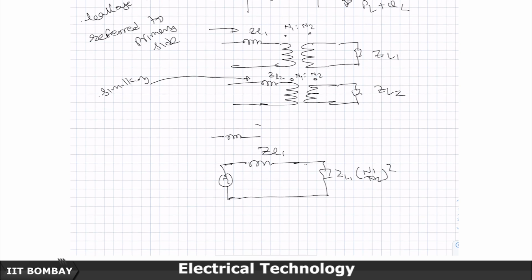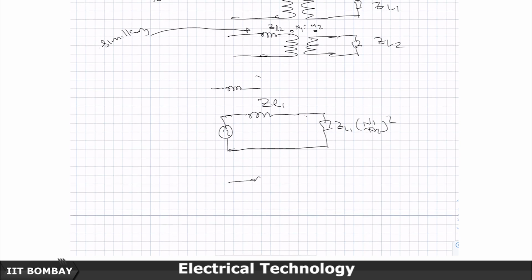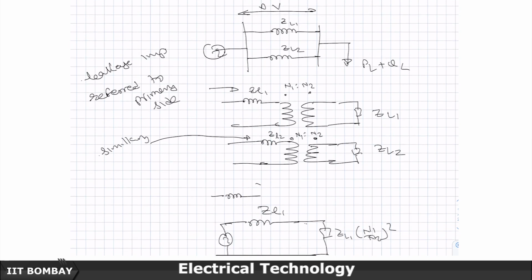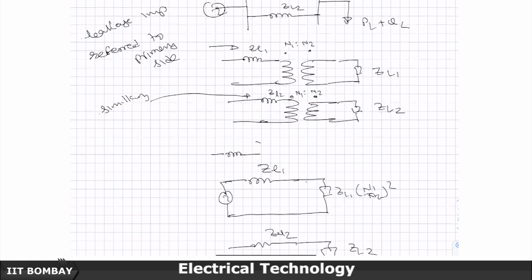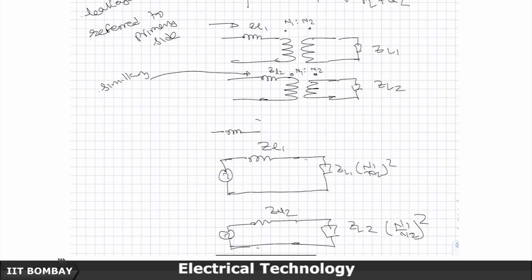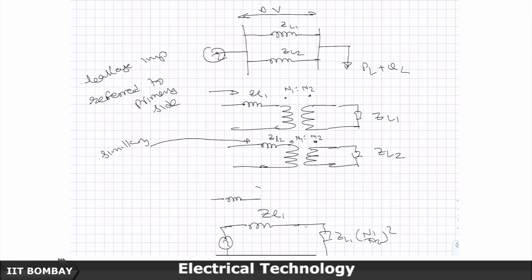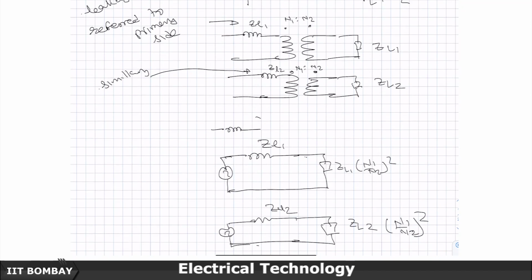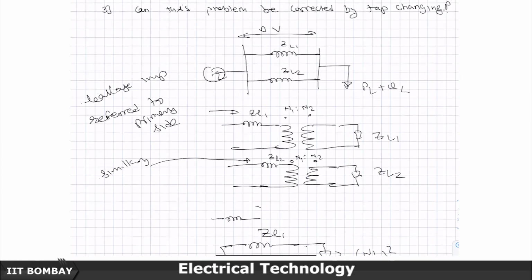So, remember I had said that transformer impedances, when you refer them from primary to secondary, this is what is going to happen. If this was not one bulk load, but two impedances in parallel or something like that, then I could have shown it like that. So the point is, you can therefore calculate the load current which is coming to these transformers.